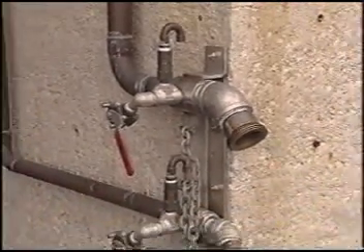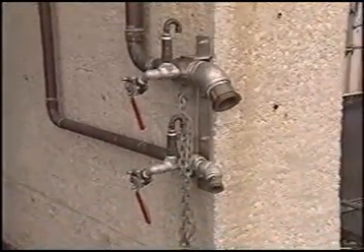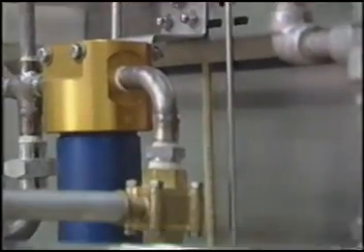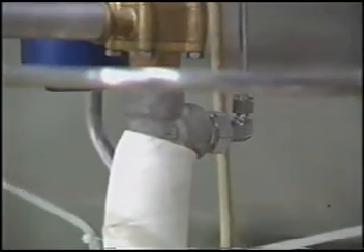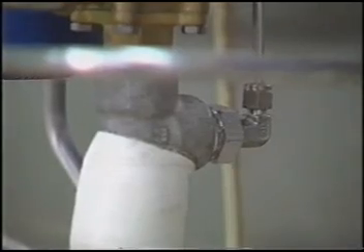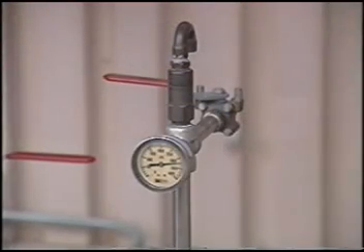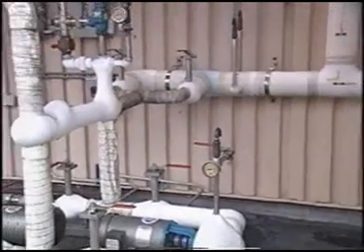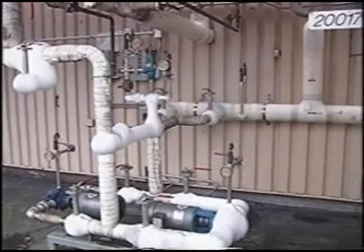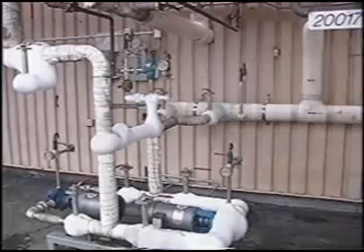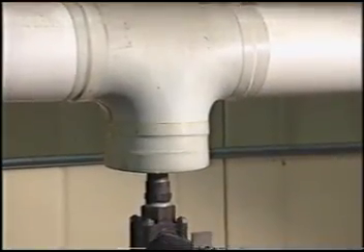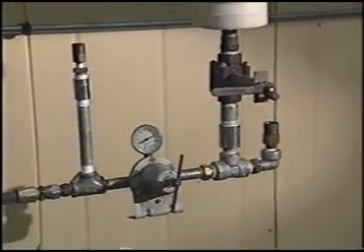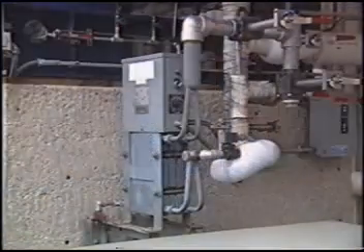Systems that handle liquid carbon dioxide should be made from materials recommended by the Compressed Gas Association, which develops and promotes safety standards and safe practices in the industrial gas industry. If your pipeline is connected to any vessels, hoses, or other equipment not rated for maximum pressure, protect it by placing pressure relief devices in the supply lines. And every pressure regulator needs backup protection downstream, such as a safety relief device in case the regulator fails.